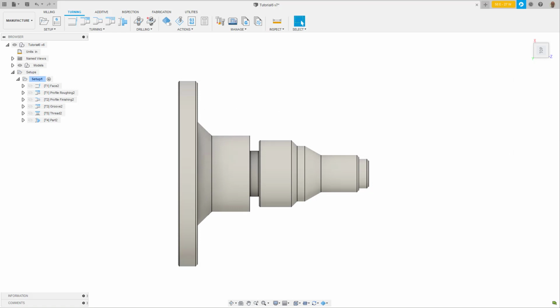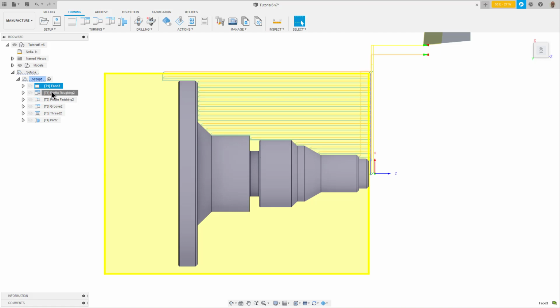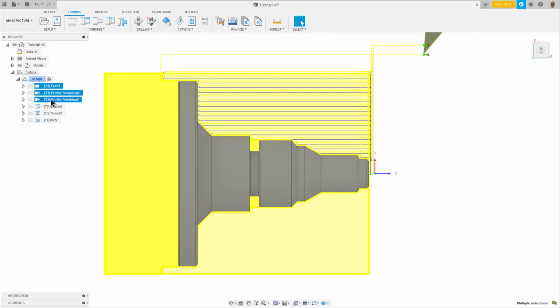You may need to post these same operations for several different NC lathes. Not every machine will have the same capabilities. You may be running a lathe with a bar feeder, and the program will require a parting cutoff operation. You may be running billets that are already machined to the proper length, so no cutoff is needed. NC program lets you create groups of operations and pre-select which post processor to use.